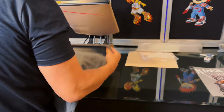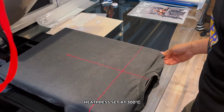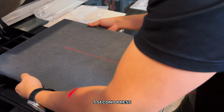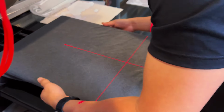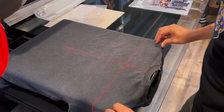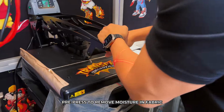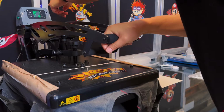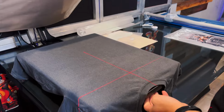So what we're gonna go ahead and do is slip this all the way through. I have our heat press set at 300 degrees and we're only pressing for 7 seconds. So first thing I'm going to do is just to make sure that everything is nice and aligned and straight. I'm gonna go ahead and take it in. We're gonna do a quick pre-press to remove all the moisture in the fabric. I have it at 9, so this is firm pressure. Pop up, let's pull it back.